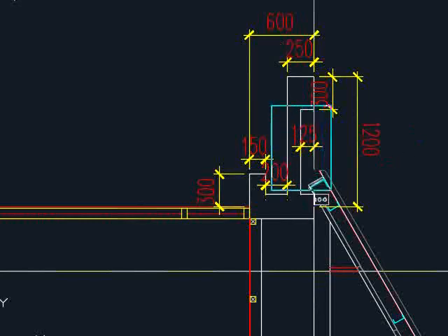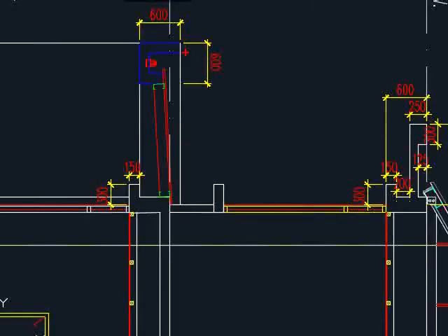Because you are dealing with this gutter, you want to prevent the leakage of the water. Therefore, you need to put reinforcement bar more closely spaced. And because this one will behave like a cantilever, make sure there are top reinforcement bar at the slab of the gutter. This is another shape of the gutter.